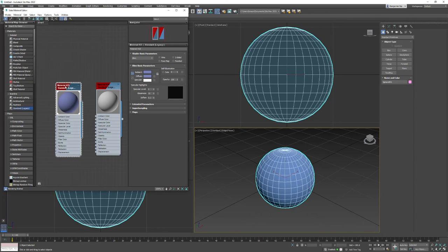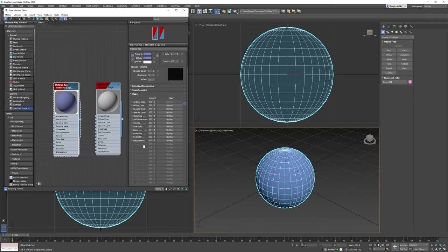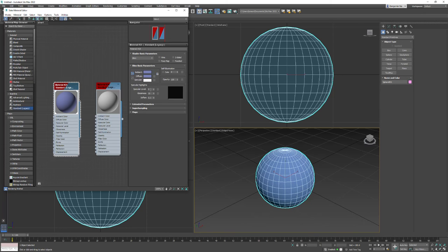In addition to being able to change colors, there's a lot more that you can do with materials. There are maps that you can assign to it, which again is not something we'll be doing much of in here. You can also adjust the specular. If I click on this spinner and drag it up, you can see how it's now shiny on this sphere.